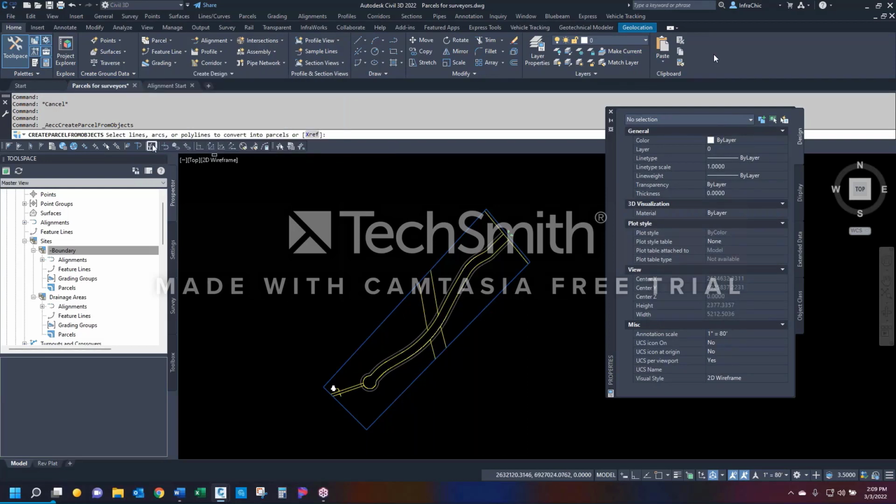And on my command line, it's going to say select the line, arcs, polylines, or convert into parcels, or XREF. So if I had an XREF in here with that polyline, I could click XREF first and then go select the line work from the XREF, and it would make it from that. It won't delete it from the XREF. It will just make a copy, like using, what's the command? Ncopy, which is copying line work from an XREF live into the file it is referenced into. That's what Ncopy does.